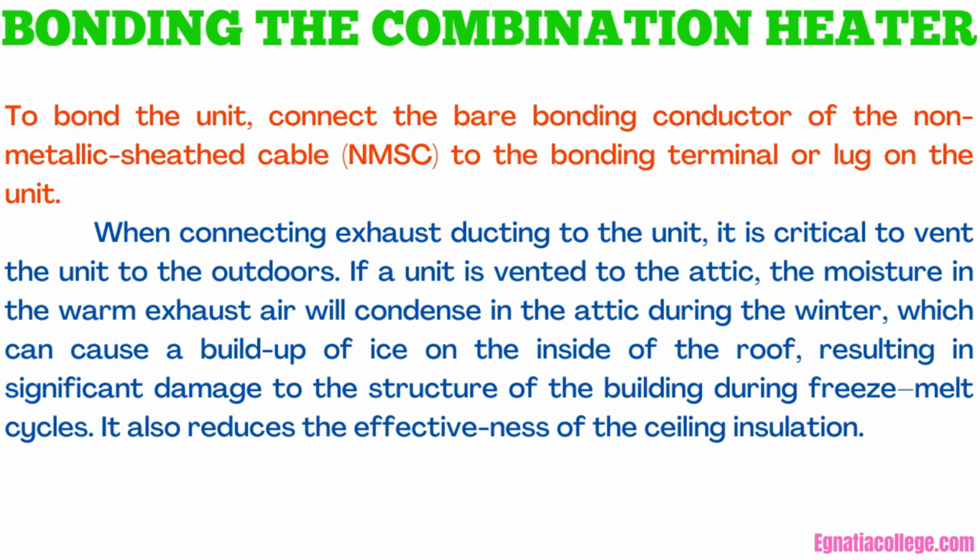If a unit is vented to the attic, the moisture in the warm exhaust air will condense in the attic during the winter, which can cause a buildup of ice on the inside of the roof, resulting in significant damage to the structure of the building during freeze-melt cycles. It also reduces the effectiveness of the ceiling insulation.